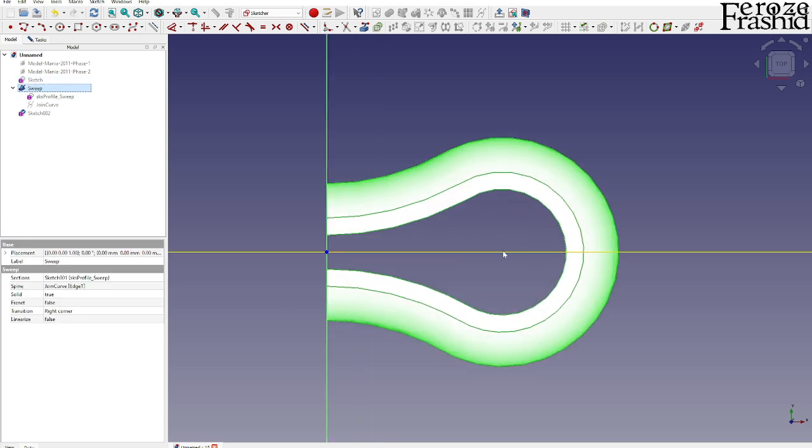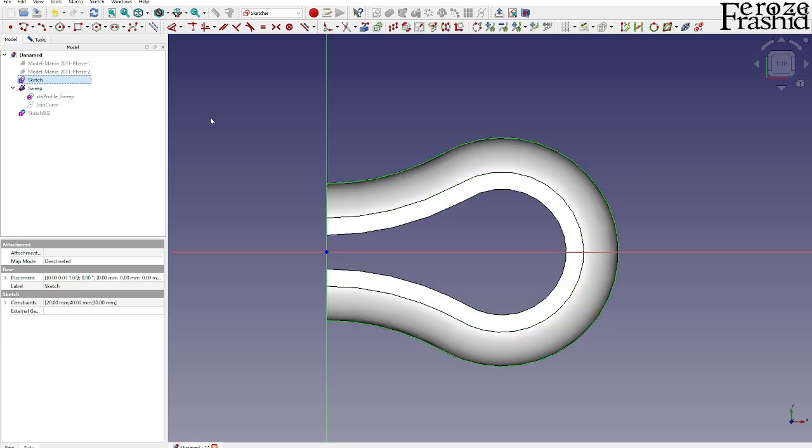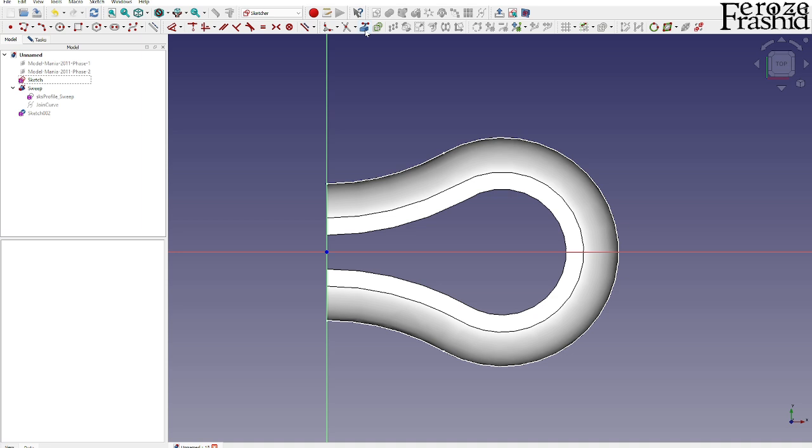On this one, I want to bring in this dot, which would be a sketch. And then take an external geometry, which is GX on the keyboard. Hit G and X at the same time and bring in this center reference. And I want to start by creating an arc by center. I will be filling in this. So this radius, I know this happens to be 11, and I want to say from here to there.